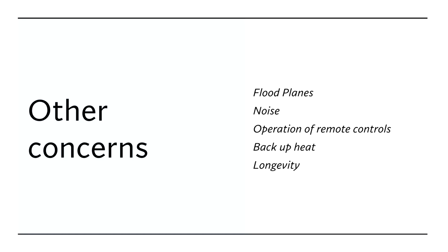I'll leave these for some real simple things here, but you don't want to put the inverter unit someplace where it's going to be prone to flooding. There is a lot of electronics in there. Yes, it's meant for the outdoor environment. They're sealed up so that they can't get stuff in there. But floods, it would not be a cool thing to have these things sitting on the ground and have them get flooded and saturate the electronics in them. So usually you want them up off the ground.